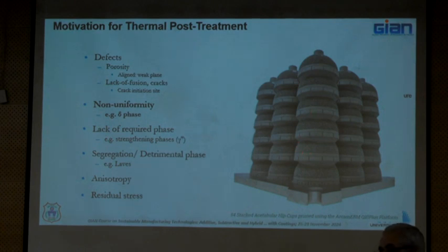That is enough to cause a phase change, right? Let's not talk about heat affected zone and make it too complicated. Because for that reason the temperature history is different, and therefore the phase constitution in each layer can be non-uniform. And you may therefore require a thermal post treatment to nullify this non-uniformity.